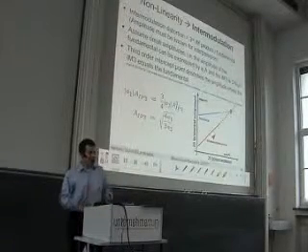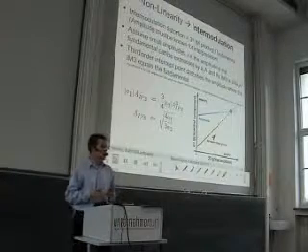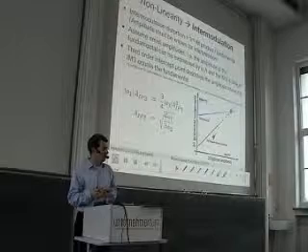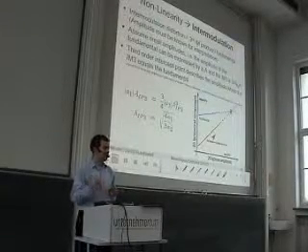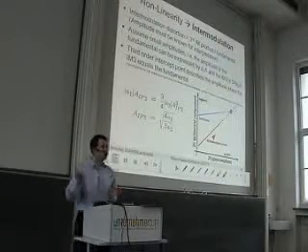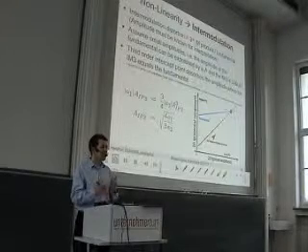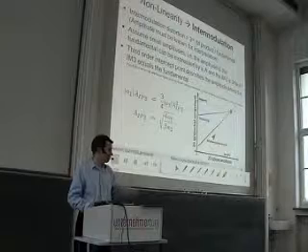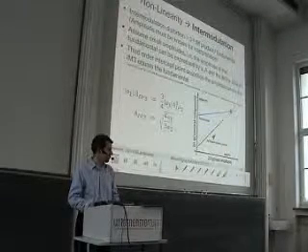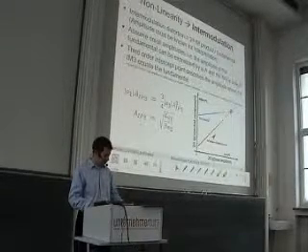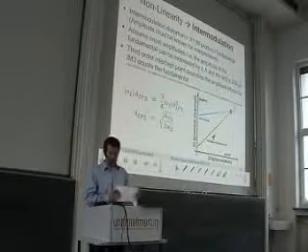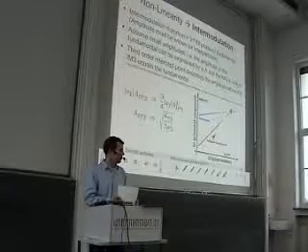And by having such plots, you can also investigate whether something is going wrong in your circuit or not. Because if any harmonic doesn't scale with A to the power of the harmonic, then something is strange in your design, and you have to search in that direction.